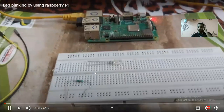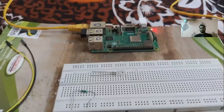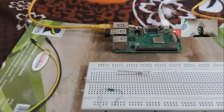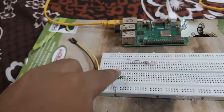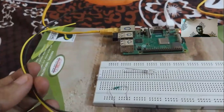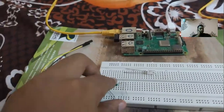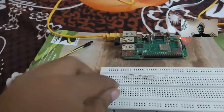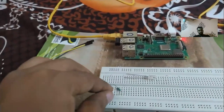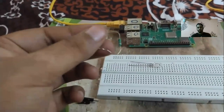Welcome all. This is our practical number one, LED blinking using the Raspberry Pi kit. In this practical we require two jumper wires, each having a female end on one side and a male end on the other. After that we require one resistor, because we are dealing with the Raspberry Pi and the breadboard. It is a must to use a resistor when you are dealing with LEDs.